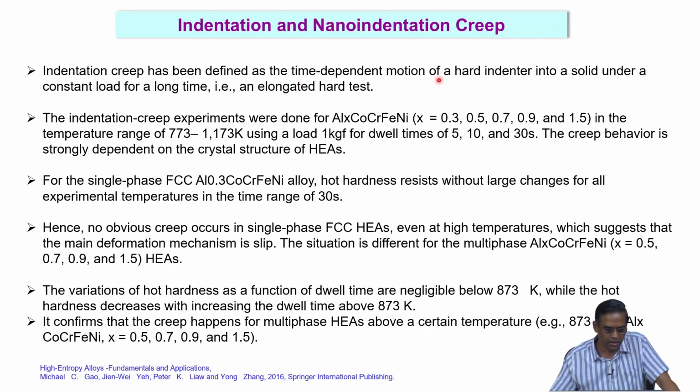So indentation creep has been identified as a time dependent motion of a hard indenter into the solid under a constant load for a long time. That is an elongated hardness test. So anything we talk about with creep means a time dependent phenomenon, right? So time dependent deformation. We will talk about creep behavior tomorrow when I show the high temperature behavior of this material. But we are talking about this at room temperature or high temperature both.